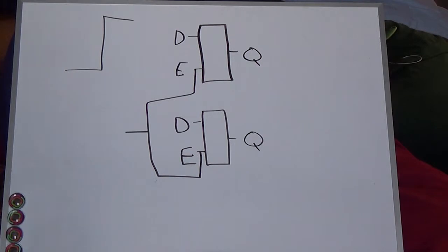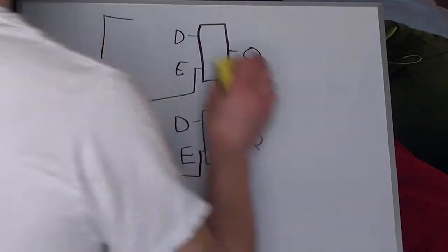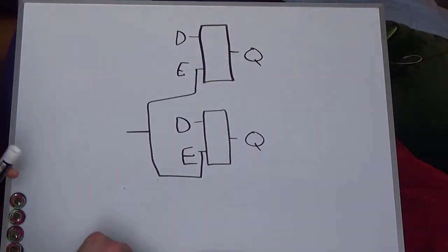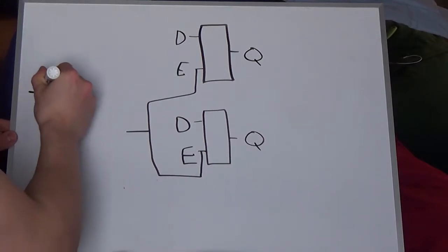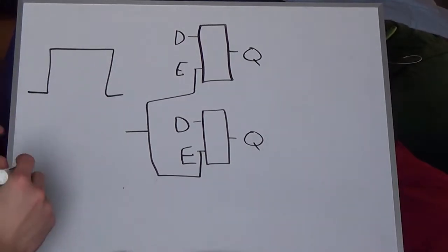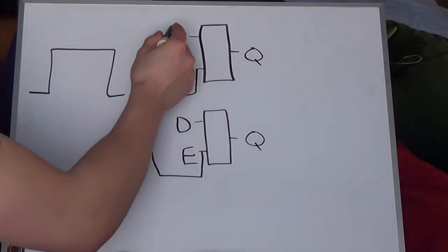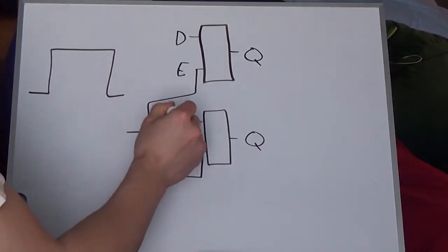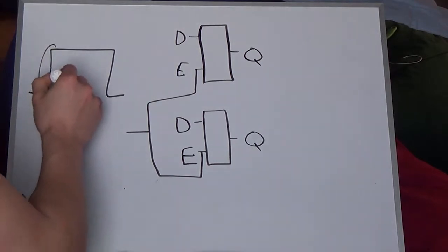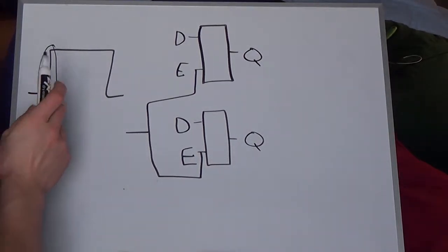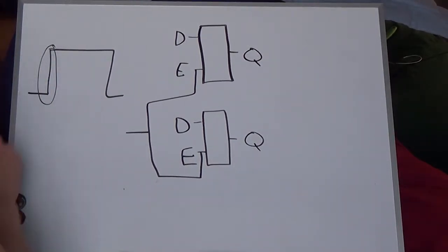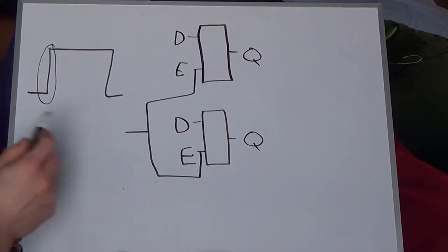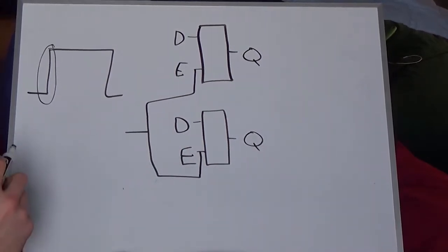And so I needed some way for, if here's the signal that's triggering this in the computer, I needed some way for data from anywhere else in the computer to be pushed onto the inputs of the positive edge triggered D flip-flop as soon as it sees a positive signal here, as soon as the signal goes high. And then I needed enable to wait a little bit.